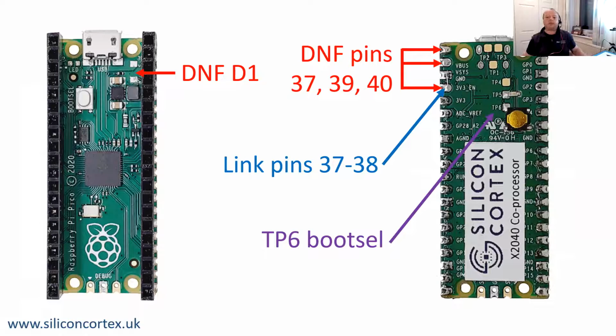There we go. I can see that better now on my screen. So on the Raspberry Pi Pico board, there is a small diode called D1. You've got to take that off. And also, before you solder that black header in, as you can see there, the 3 pins, you need to pull them out, so you're not soldering to those.